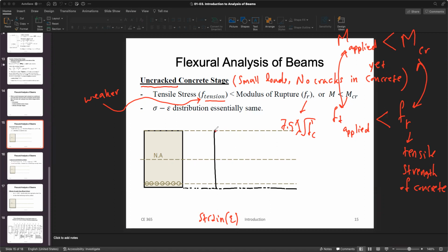As you have seen before in your mechanics of materials, you are going to have some compression on top, right? The maximum compression deformation would be on the farthest fiber away from the neutral axis. You know that it's going to approach 0 on the neutral axis, and then you're going to continue to reach maximum tension at the other end. All right. So this would be your strain.